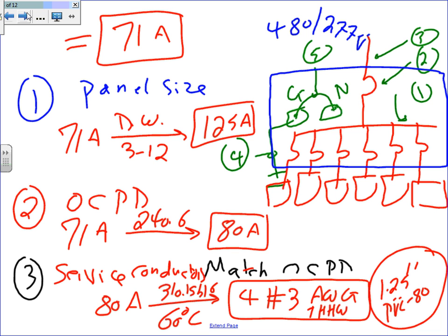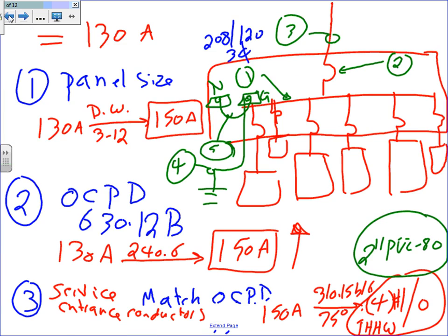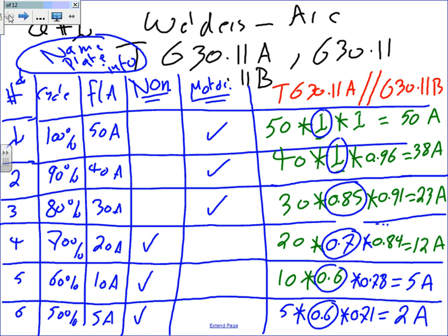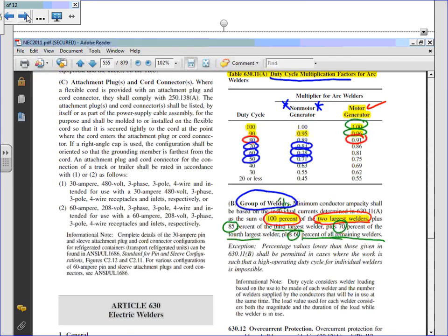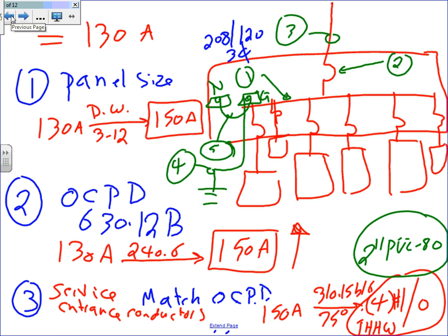I want to remind you, Chris, that, well, it might be a good example, 41, because the amps will be different here since the voltage is different. Let me just go to the first example that we've done. The first example was 28120, right? Perfect example. In this example, we came up with 130 amps. That's a load. Now I want to grab a chunk of light and throw it onto the same panel. A chunk of light and receptacles. That's what I want to do.